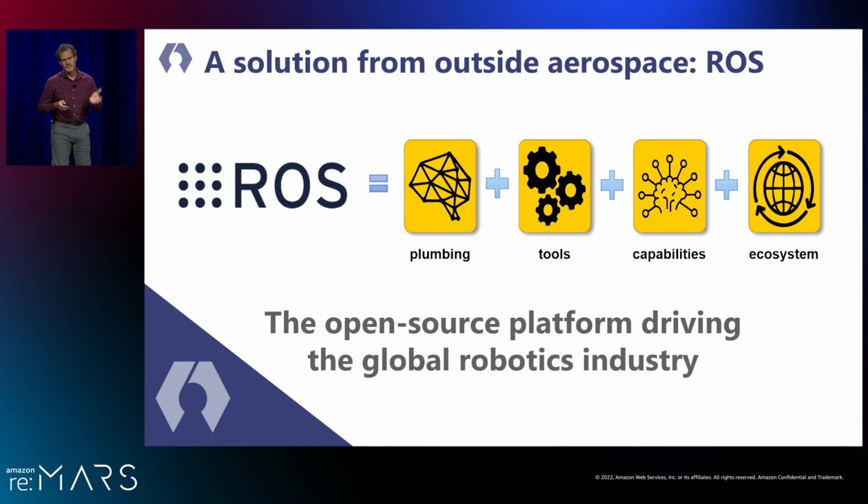So, for example, ROS has a whole ecosystem of packages. There's a package like MoveIt 2 that can plan and execute motion for manipulators, like the Canadarm, for example, or those hands and fingers that we saw on the Robonauts. There's another package called Navigation 2 that can provide the means for robots to plan and execute paths and avoid obstacles and travel from point A to point B.